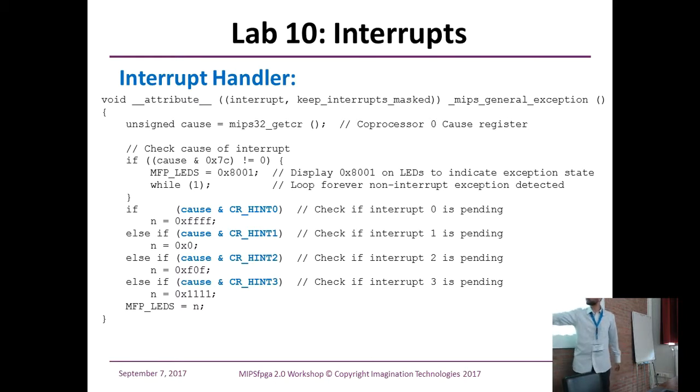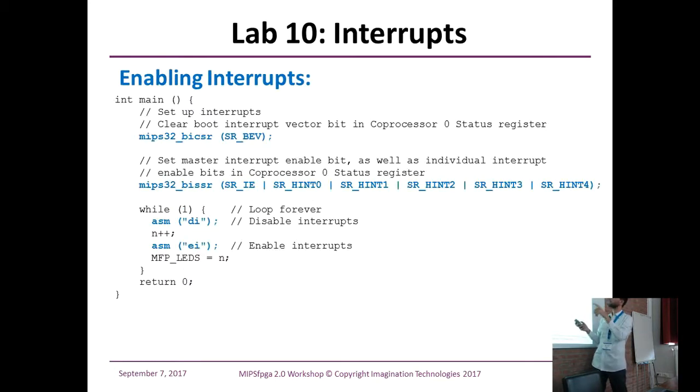MFP_LEDs is another variable. You store the value of n here. So this happens in the interrupt service routine. This code only runs when you press the push button and you've loaded the program code. Then when you press the push button, it happens once. Okay, so now we look at the main function.